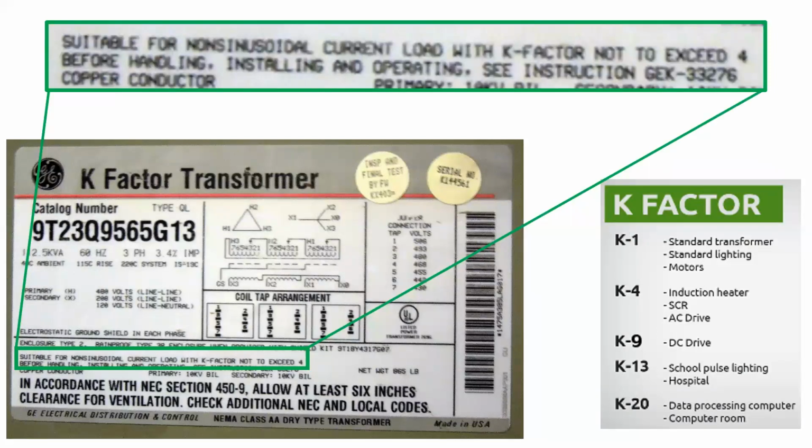And we can see listed here the K factor, and it says there is a numeric value there. This isn't something that we have to memorize, but simply know that the K factor is a numeric value given on a transformer, K1 being the very lowest, so least ability to handle harmonic or nonlinear loads, and the highest numeric value, K20, would be something that can handle significant nonlinear or harmonic disturbances without sustaining damage.